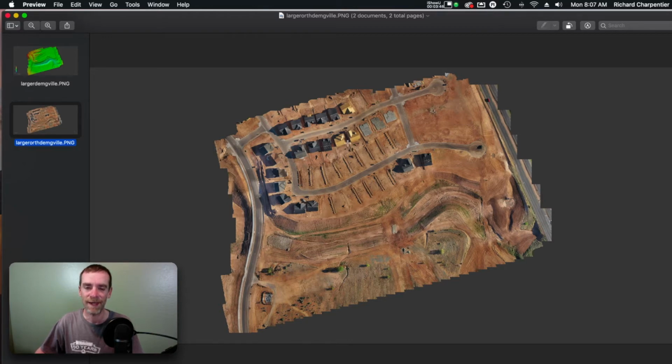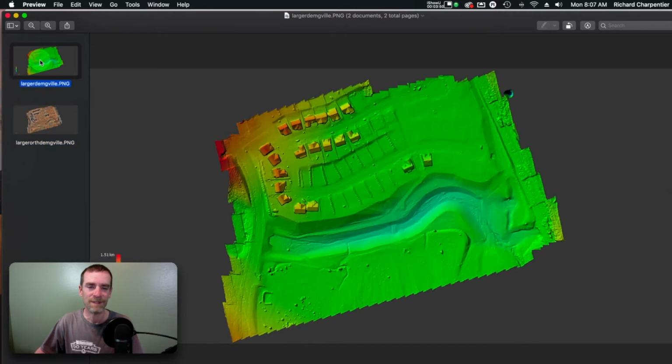So we're looking at these homes here. We know that we've got this drop off here, and let's pull up the digital elevation model version. Do you see where the water's probably going to be flowing during monsoon season? Because I sure do. So the digital elevation modeling can go a long way to helping construction groups that you're working with, just to show them very quickly and visually, here's where the height of land is, here's where the lower points of land are.